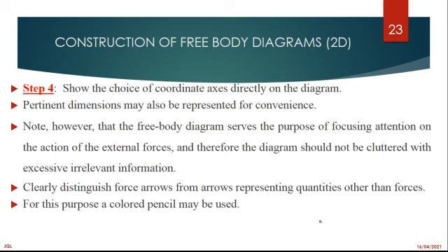Note, however, that a free body diagram serves the purpose of focusing attention on the action of the external force, and therefore the diagram should not be cluttered with excessive irrelevant information. Don't make your free body diagram like you are an artist drawing something. If you put a lot of things, you end up getting confused. So in a free body diagram, just put items that are necessary. Put the forces that are necessary. Put the dimensions that are necessary. Put the signs and the angles that are necessary. Not everything.